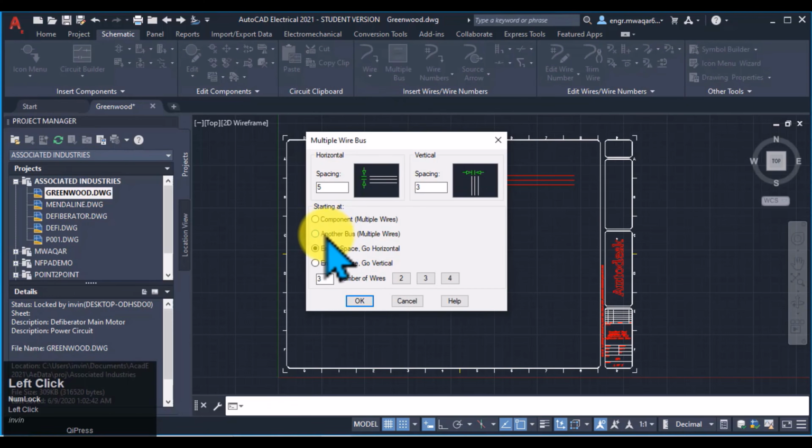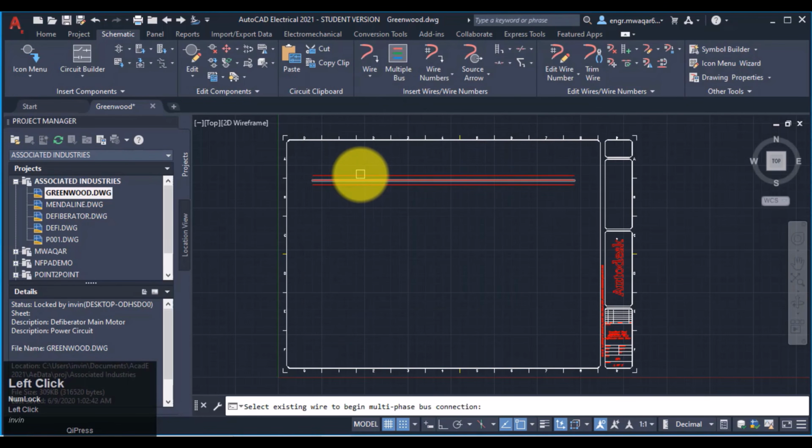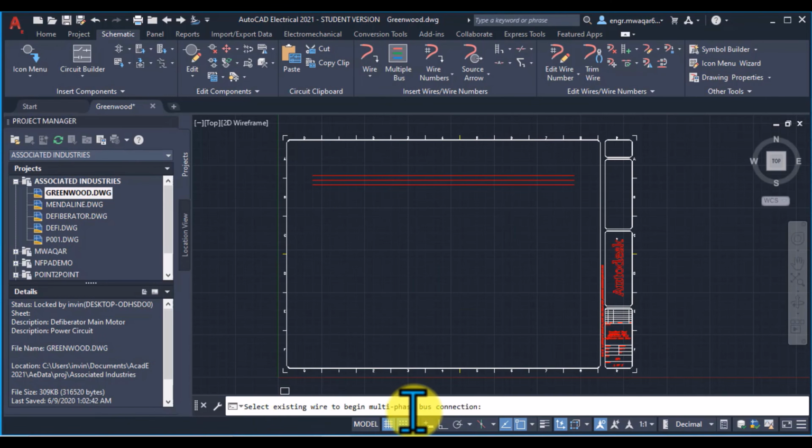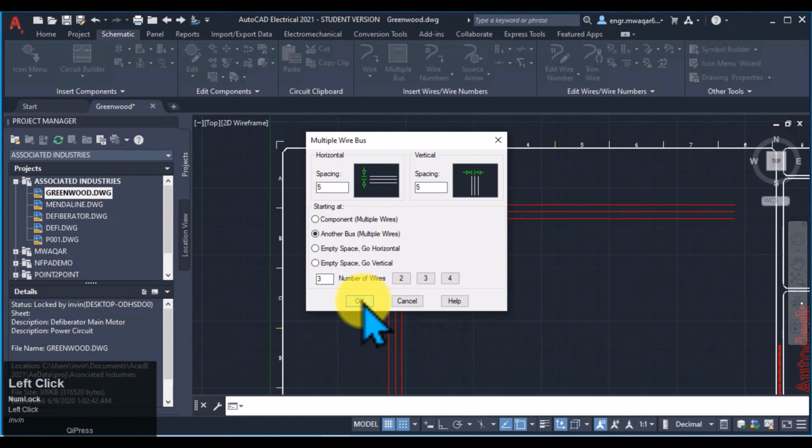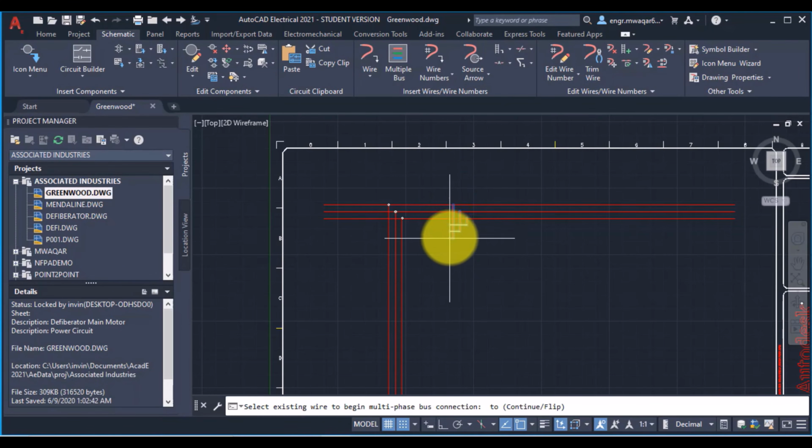The numbering format itself is powerful too. This concept of replaceable parameters. We saw things like %. It's a simple code. % puts the sheet number in, % puts the sequential number in. So automatically, a wire on sheet 5, line reference 10, becomes wire 510. You don't have to think about it. If you move that circuit to sheet 6, the wire automatically renames itself to 610. That saves. I mean, how much time does that actually save?